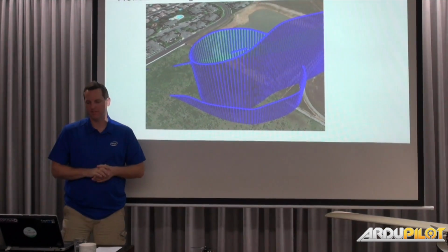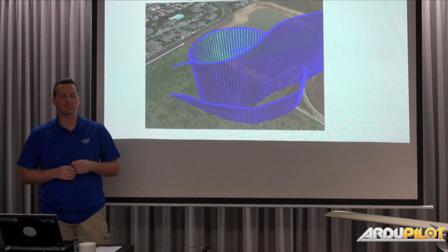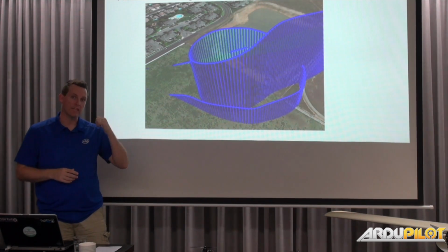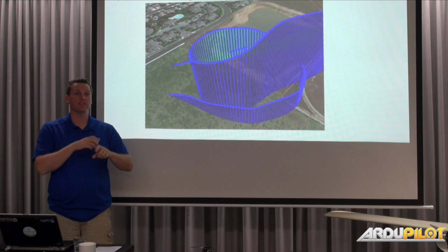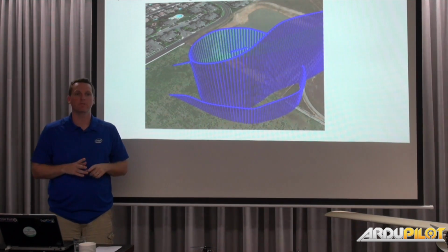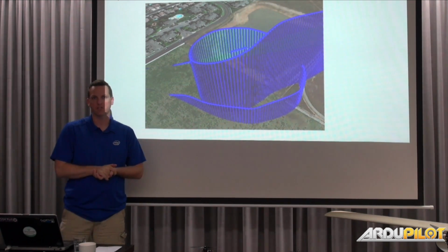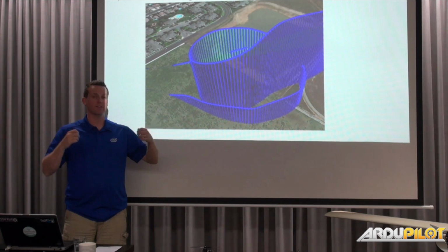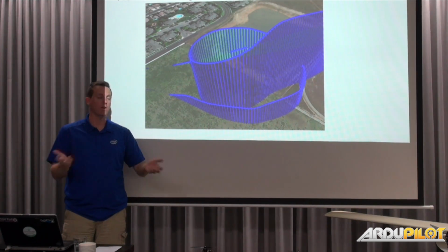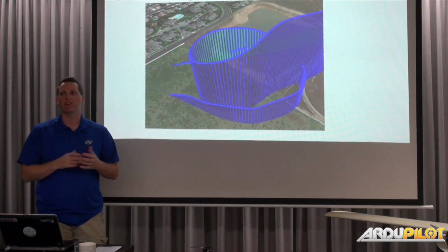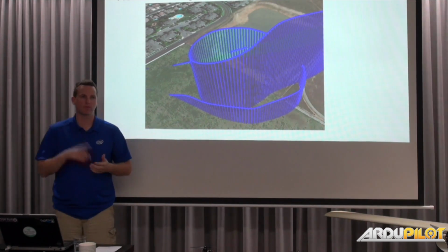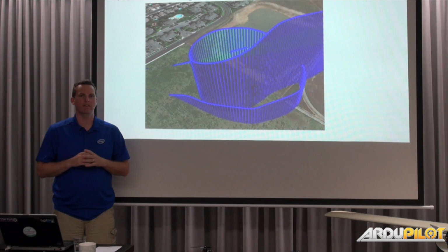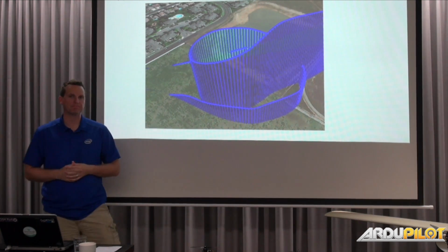Yep. And so this was a little bit of instigation he was doing, or the inspiration was this and that. So we have a deep stall in there, and the idea is on the helical landing, it'd be the same thing. You just have a land point, and it just figures out the radius. It figures out all these things using the existing parameters that you've tuned for your aircraft. So you just say, the idea is long term to be that land mode. So you just say, switch the mode, and it just comes and lands. And it's the way you want it to be. It's very hard to do on a generic aircraft because the ArduPilot is so versatile for all kinds of things. So it's hard to do that in a generic sense, but that's the plan.